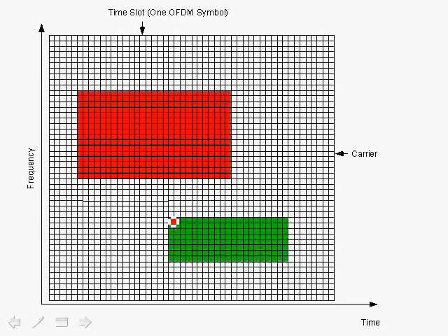Consider the next picture where we show a region within the grid. Consider the red region here. Using 802.11a as an example, each carrier here would represent at 54 megabits per second 6 coded bits. Now, ignore all coding for now and just consider the case where we have an OFDM system in which each carrier contains, for example, 6 bits of data.